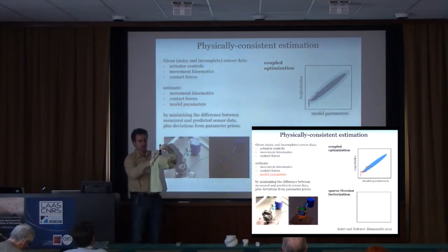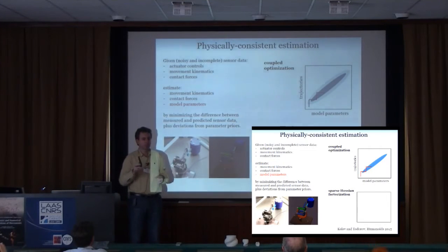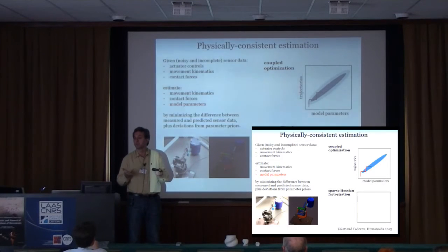So now suppose I'm holding this thing, but my Vicon system tells me that my fingers are open by 1 millimeter. Now my system ID engine is going to look at that and say, oh wait, you're not touching the thing, therefore the thing should be falling. But it's not falling. What's going on here? Please explain it to me. And then it has to invent something. In particular, it might invent that the gravitational coefficient is 0 to explain that.